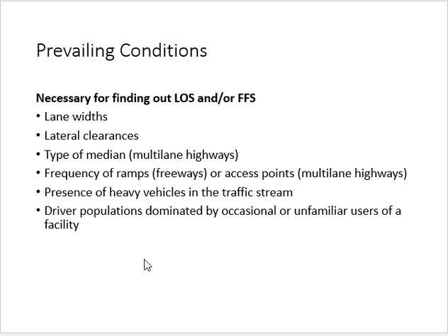Access point means entry. From this access point, I can enter this road, not the next road. Got my point? So an access point is always unsignalized, and it is always entry from a minor road in one direction. That's it. You cannot cross it. There is no crossing. On an intersection, there is a crossing, right? So an access point is that point from where you can enter and exit the highway without any signal, and it's always for one direction. There is no crossing. Clear?